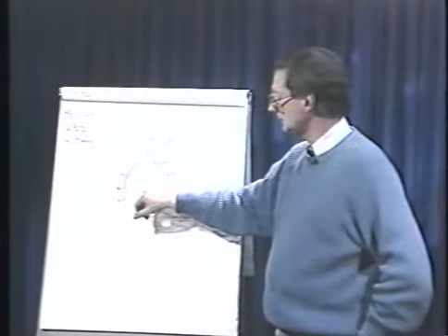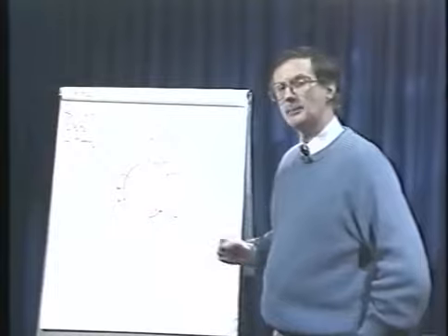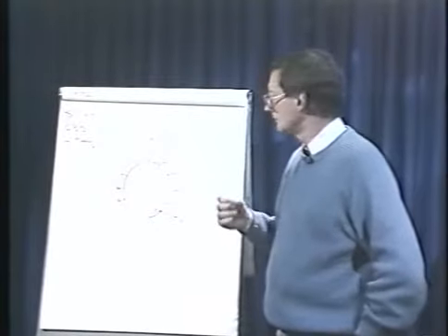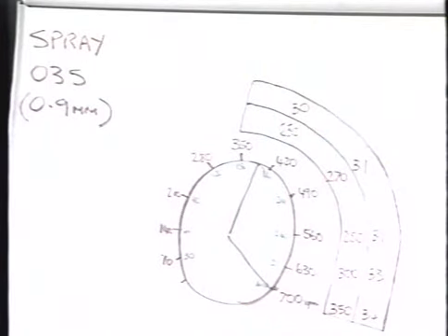An ideal starting point with an 035 wire on many applications, 1/8, 3/16, a quarter, would be to set the wire feed in the middle of its position, the 3 o'clock position, 560 to 600 IPM or 240 to 250 millimeters per second. You would have about 280 amps and 31 volts. That's an ideal simple starting setting.